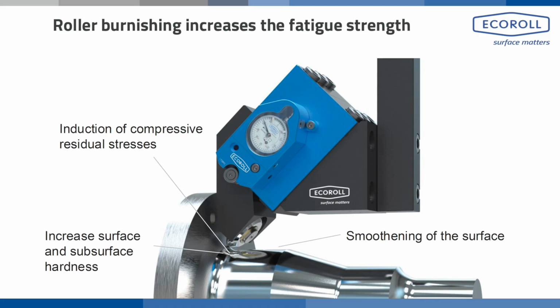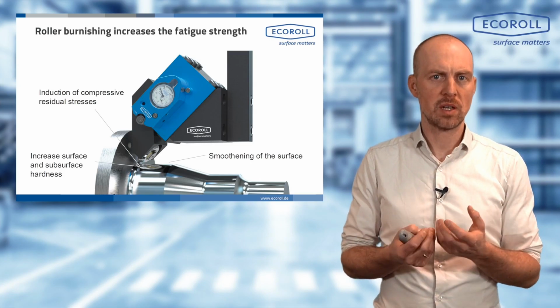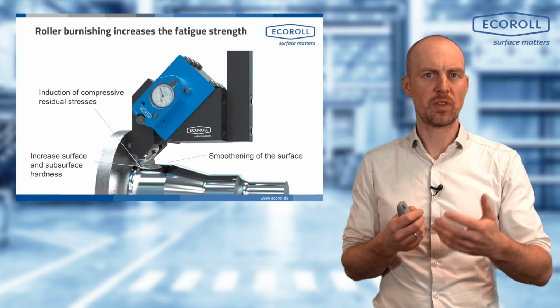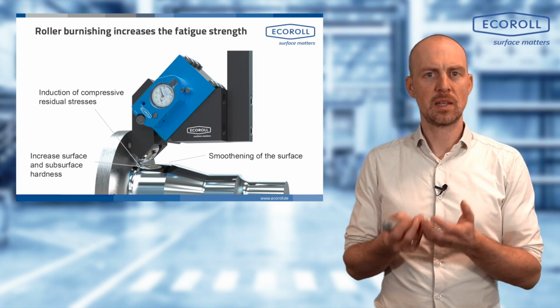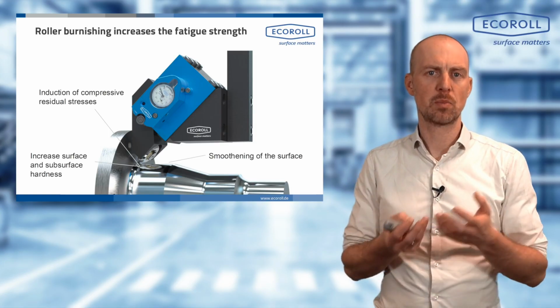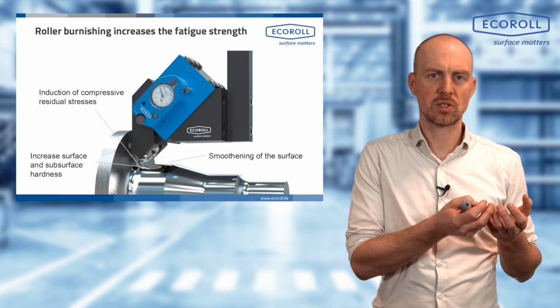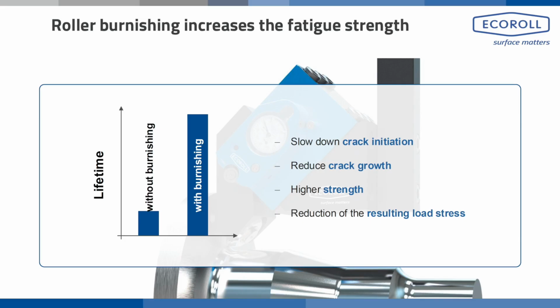Deep rolling itself is a process that strengthens and changes a component through mechanical stress. A rolling roller or a rolling element is pressed onto the surface of a component by mechanical force, rolls off there, and creates a plastic deformation of the surface. In the process, the surface is smoothed and compressive residual stresses are introduced and work hardening occurs, so that the hardness in the near surface area increases. The result of this is that we have a significantly increased service life.